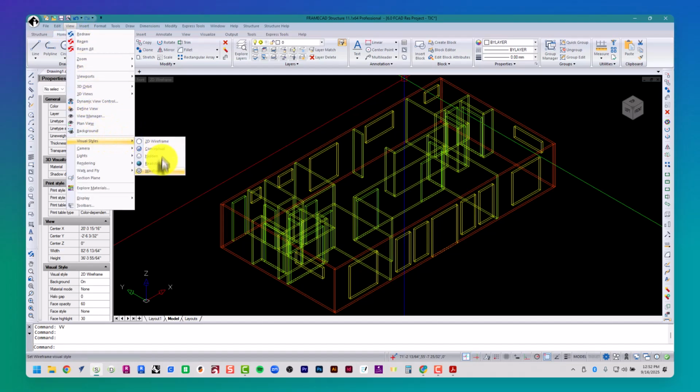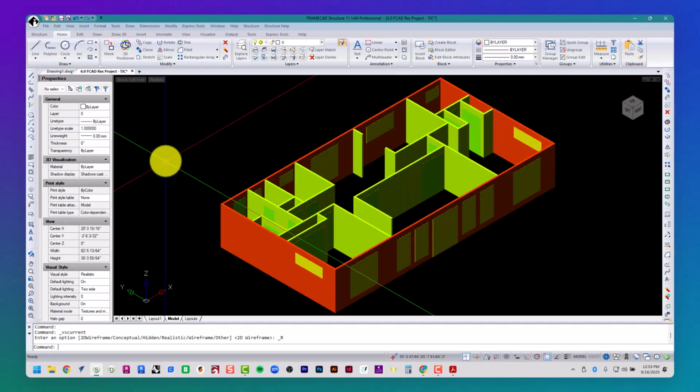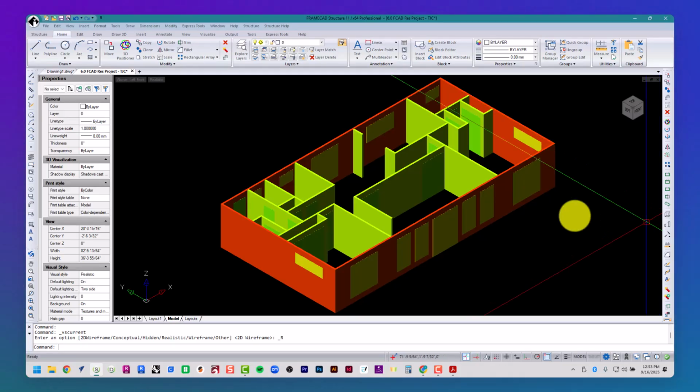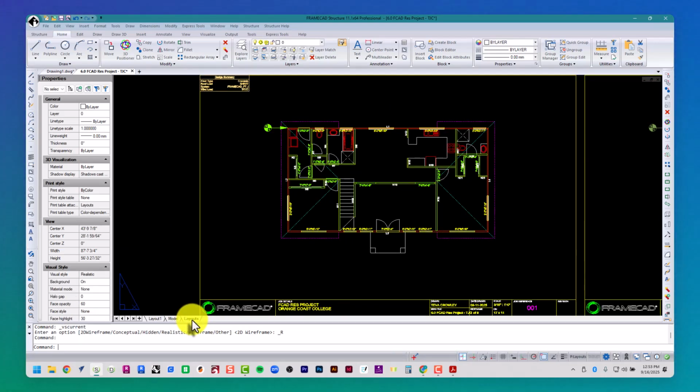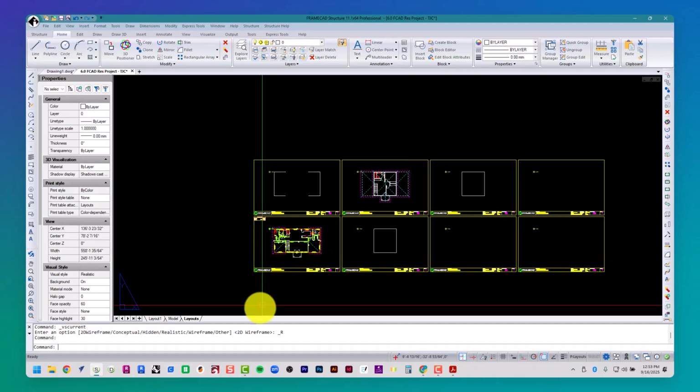And that's how you add windows, add doors, and do integrity checks, and create a 3D preview. To get back to where we just were in the 2D world, you're going to click on Layouts. And now you're back where all your borders are. To revisit your 3D model, you're going to go to the Model tab. If you make any changes here in Layout, let's say I delete N13 completely, and you go back to Model, notice that it's still there.